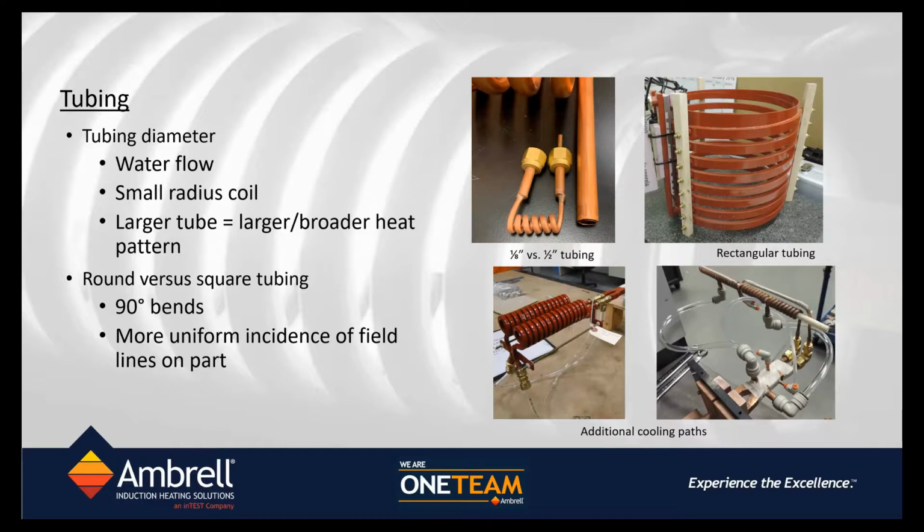So a lot of times, water bypasses are incorporated in sections of the coil so as to have cold water being supplied to the induction heating coil. If there were no bypasses and you were trying to run high power and high currents through the induction heating coil, the water flowing through the small copper tubes is going to heat up and basically boil inside the coil.